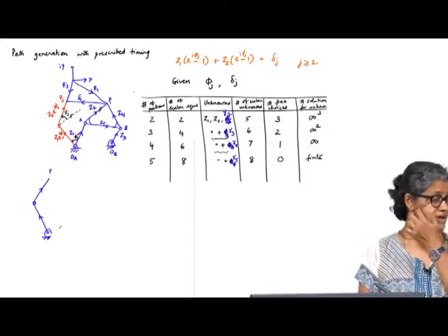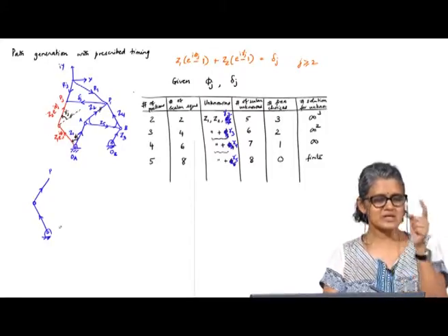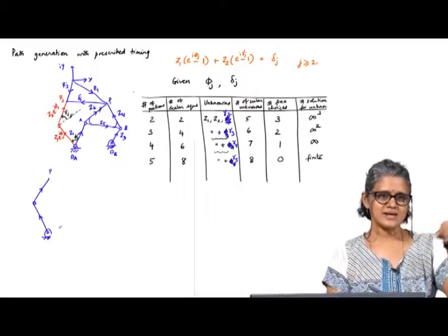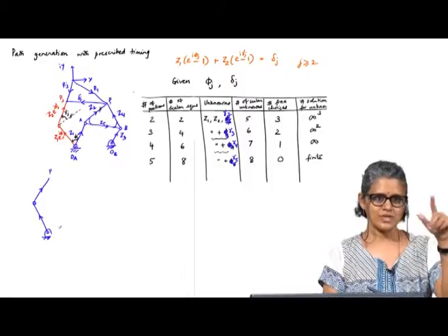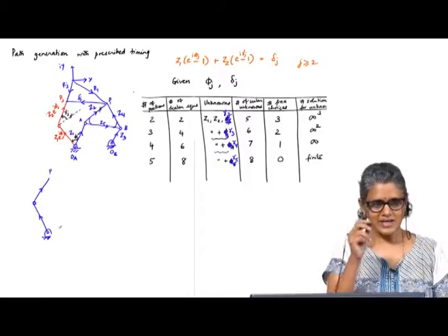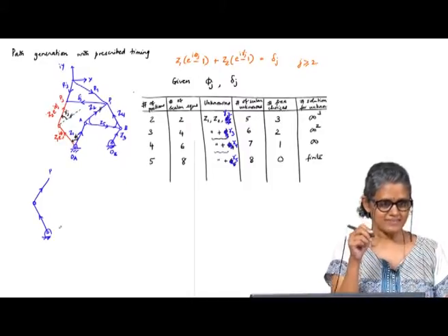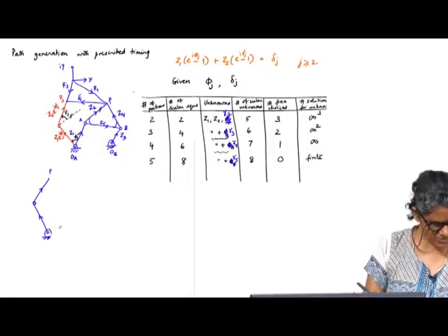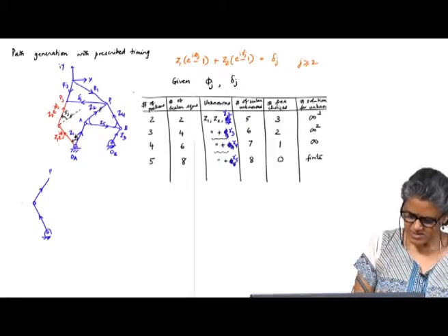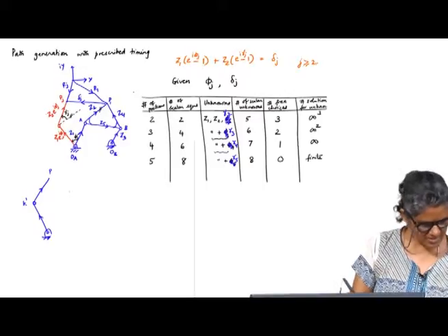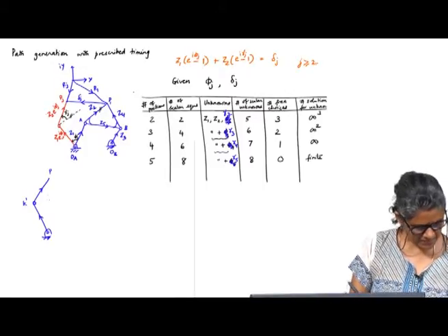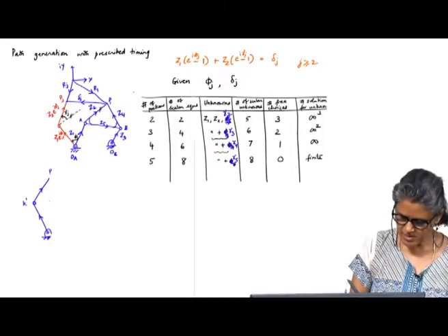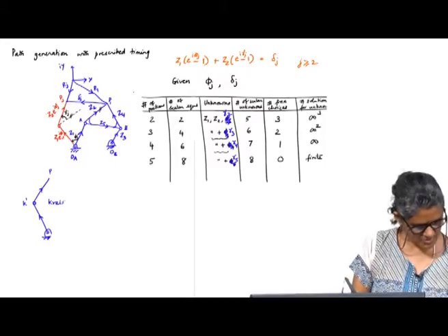Okay. And these are usually denoted as circle points. Remember, when we did the slider crank synthesis and we drew the locus of the locations, I designated the circles as K. That again comes from the circle points being denoted by K, they are called Kreispunkt.